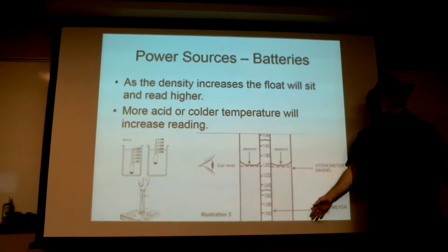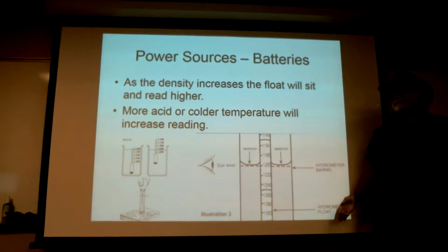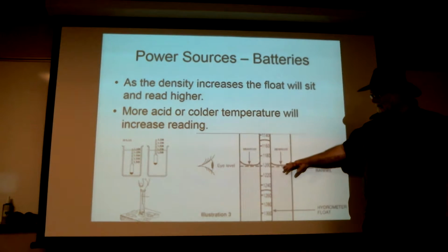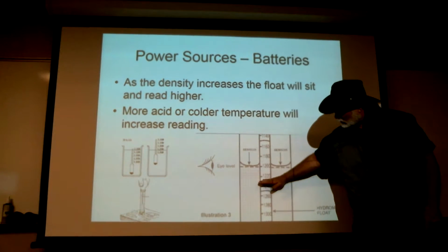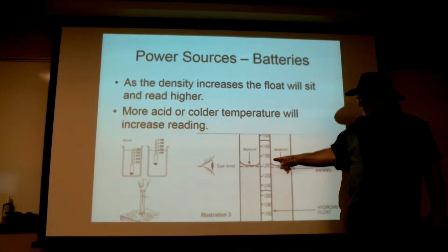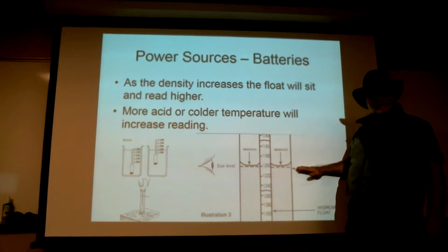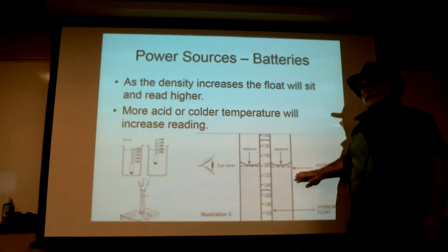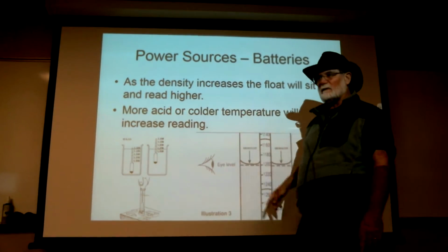It's still not in the green. If I'm right about in here, it's probably charged. So it needs to be recharged if it's here, regardless of whether I read up here or read there. But for the FAA test questions, remember, don't introduce parallax, don't introduce error from the meniscus.